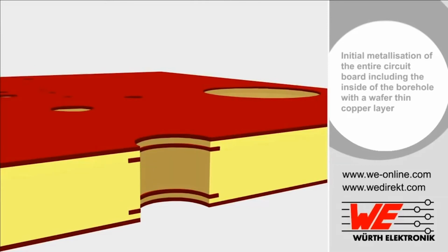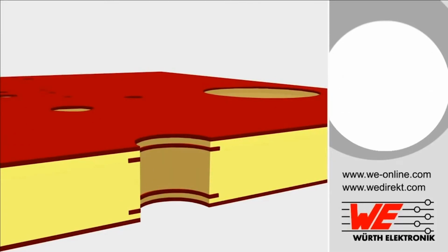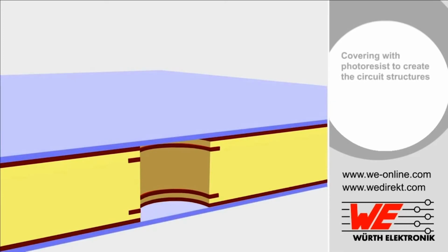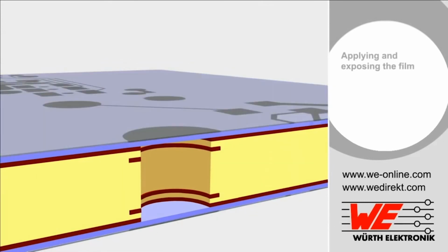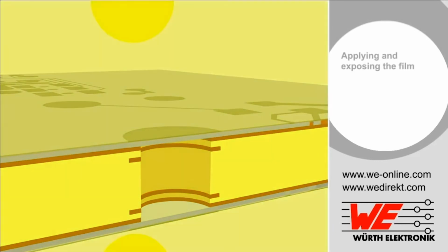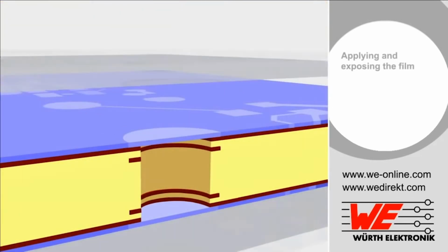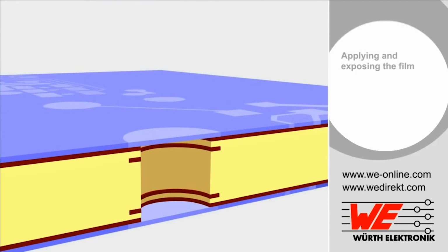The outer layers are then processed. Firstly, a laminate is applied. This lamination process is similar to the inner layer process. In the photopositive method, the areas that are not needed for the PCB layout are exposed. The aim is to expose the areas that will subsequently be plated.